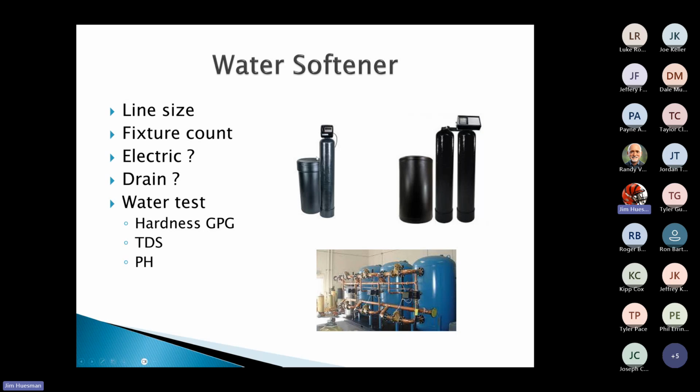So if it's a pet store, a single tank, no one's going to be there at 2 o'clock in the morning. But if we move over, same water, same building, and say maybe it's a little bit of a hospital where there's 24-hour care, we're going to need a 2-tank system.